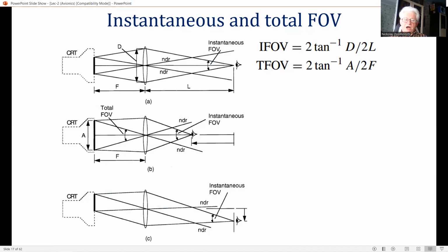However, this is not practical with the conventional type of HUD using refractive optics. This is because of the cockpit geometry constraints on the pilot's eye position, and the space constraints on the diameter of the collimating lens.